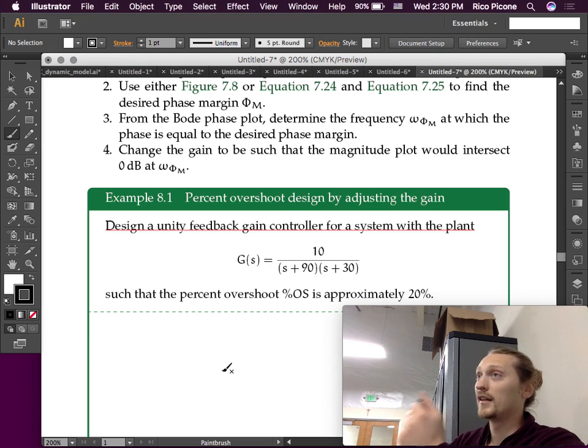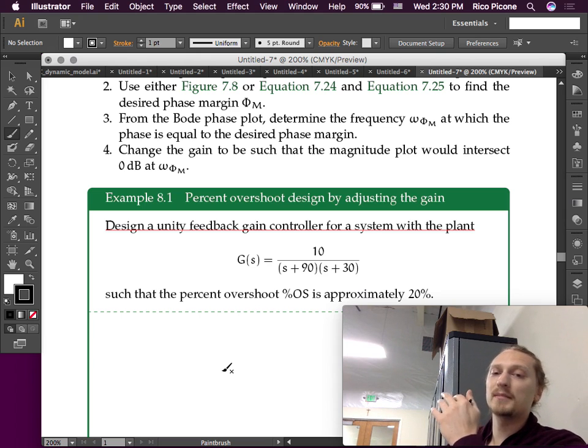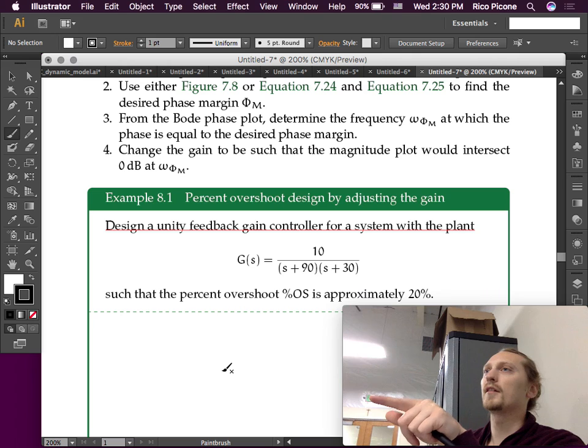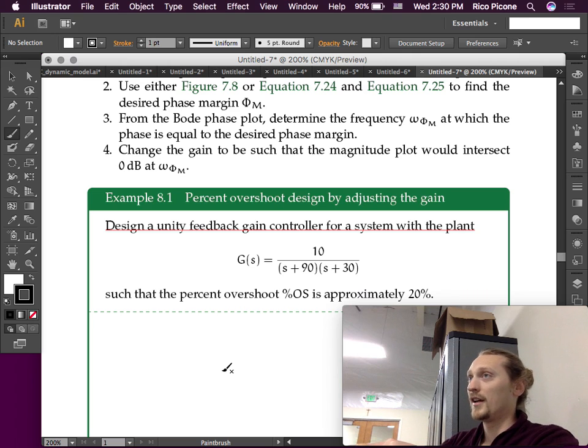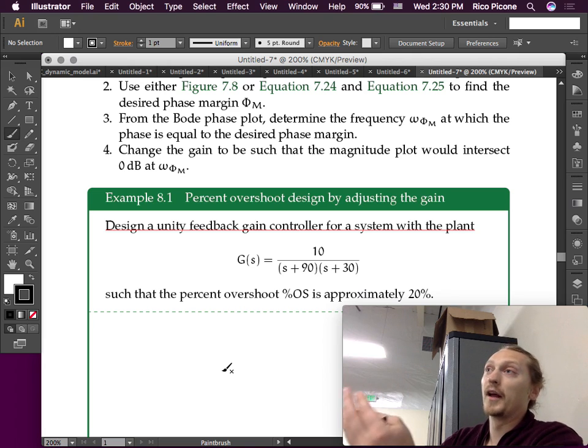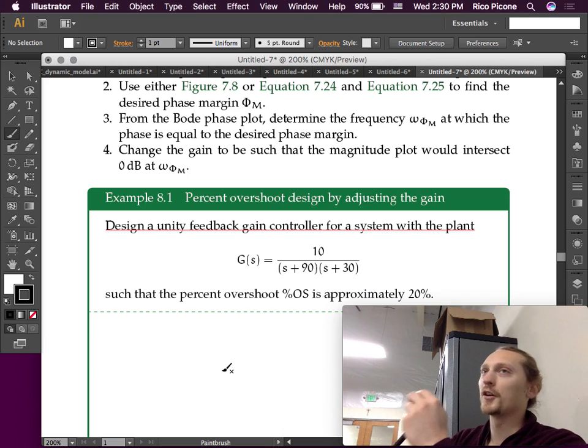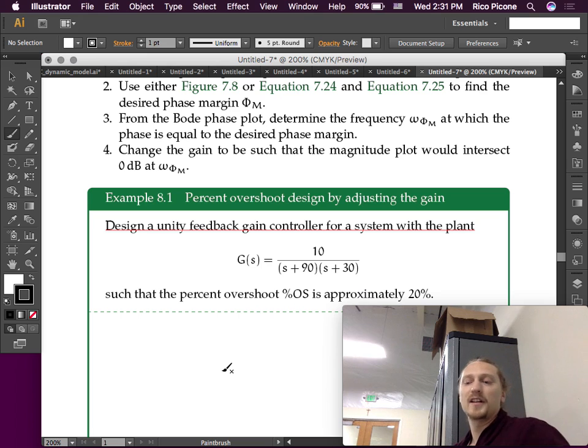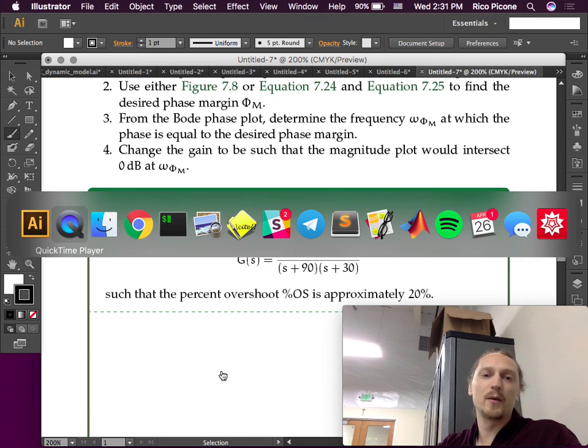But we don't need that. So we know the open loop is stable. But it could have a clockwise encirclement of -1 on the Nyquist plot, which could make it go unstable at a certain gain. So we would expect that low gain of the system is going to be stable, but it's possible that at high gain it's not going to be stable. So let's take a look at the Nyquist plot first.